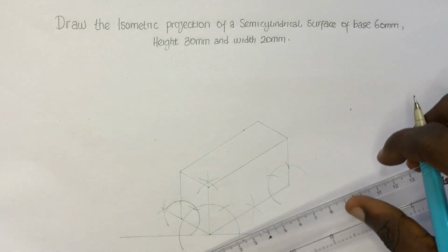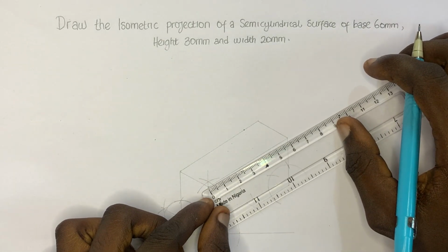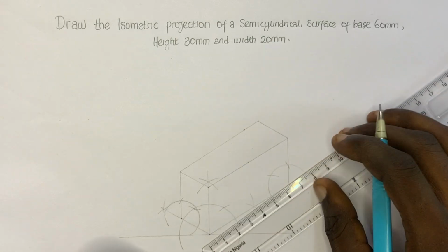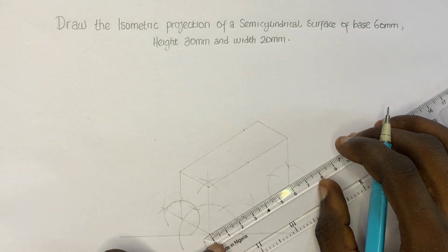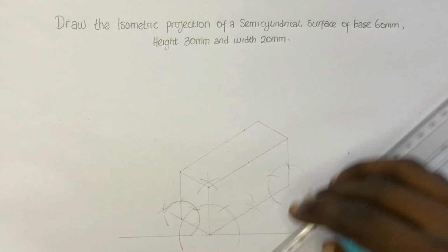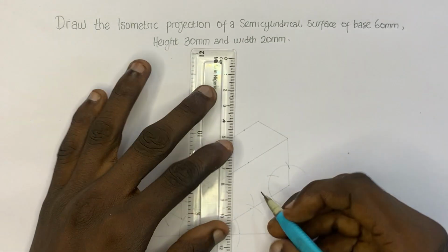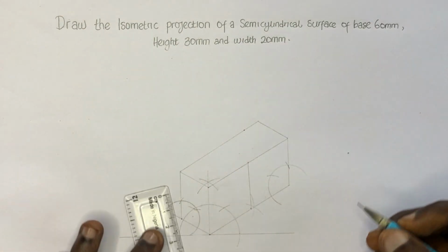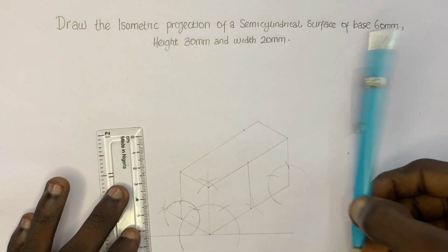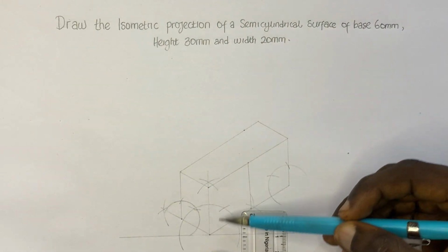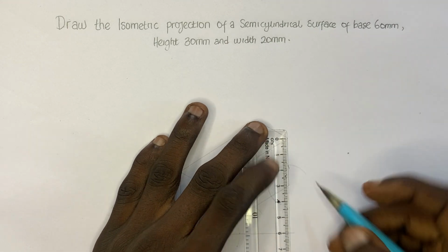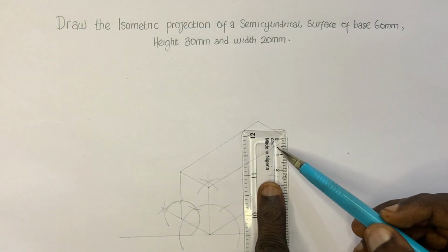Now in order to draw a semicircle here, we have to mark the center here and also mark the center here. Okay. We'll draw a straight line through it. As I said before in my previous video, to draw a semicircle we need to complete this side to be as equal a square as this.